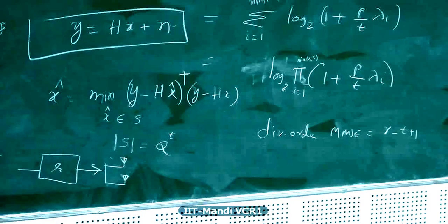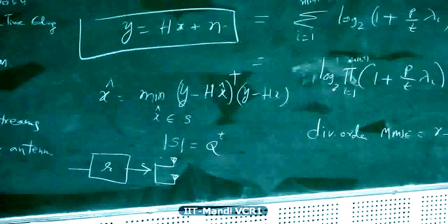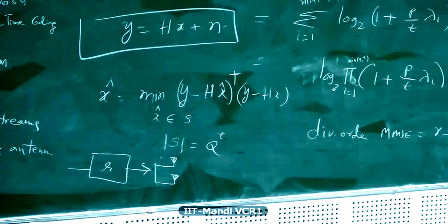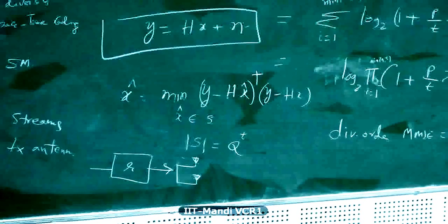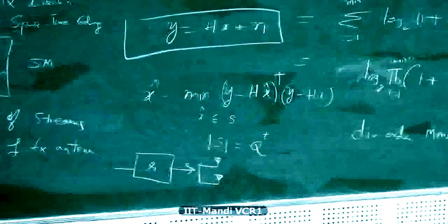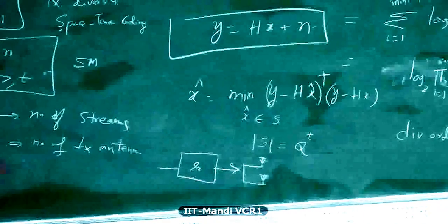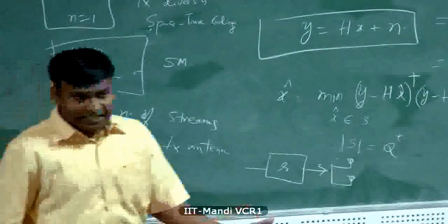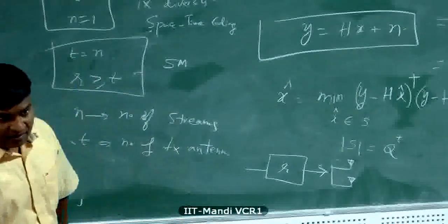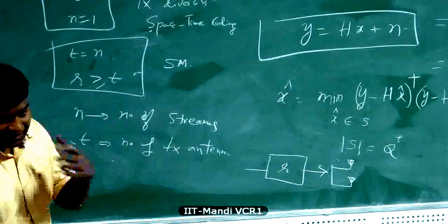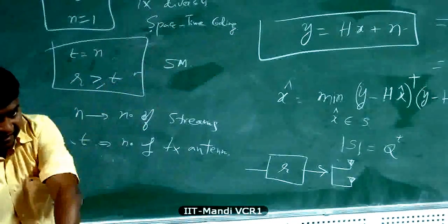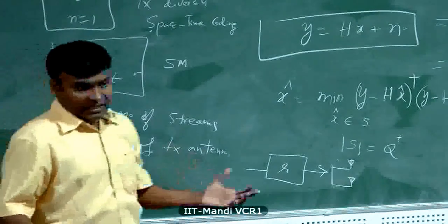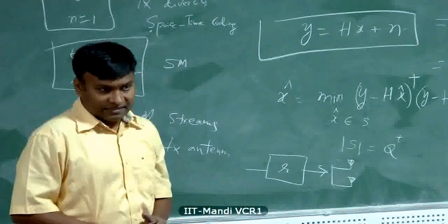In fact, this transmit diversity of space-time coding was very hard some 10 years ago. There are thousands of papers on it. Of course, there are also a lot of papers on the other topic, but this subject alone was quite hard for some time. That is, you send a single data stream. You can have any number of antennas, 2, 3, 4, and the receiver has possibly one antenna or two, any number. Preferably, the setting we are going to consider is more antennas at the base station and a single antenna at the receiver, and it's a narrow band channel, and you want to give diversity.